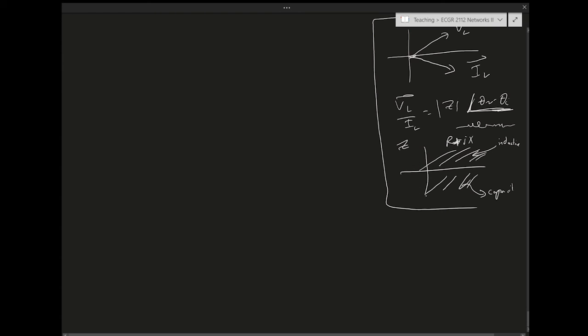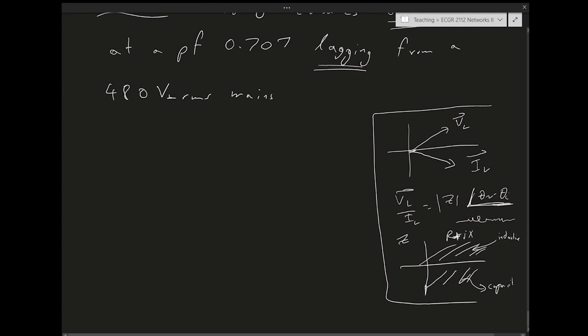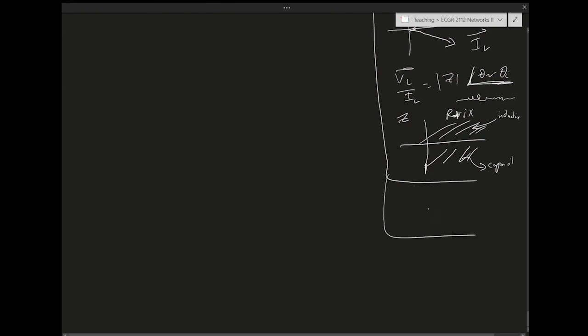Again, typically the maximum angle of the impedance, between the voltage and the current, is always going to be 90 degrees. We've established that, because the maximum angle could be either inductive, j omega L, or 1 over j omega C, which is minus j 1 over omega C. Whenever we have resistance, we get a mix, so we get a smaller angle than 90 degrees.